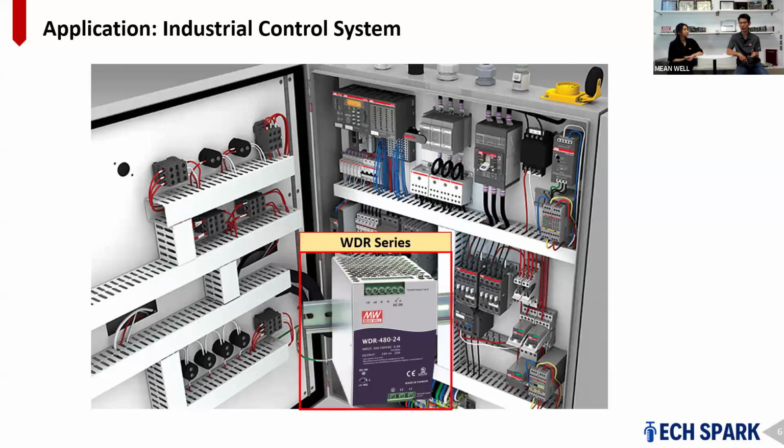The industrial control panels that manage high power machinery such as motors, pumps, compressors, and large converter systems typically require significant power. So the SDR 960 for single phase and TDR 960 for 3-phase are suitable to install to power those applications. Of course, the TDR and the SDR are also UL 508 approved, so typically they are good for industrial control equipment.